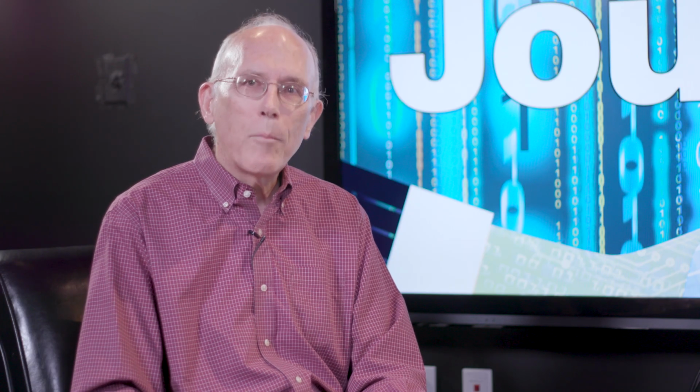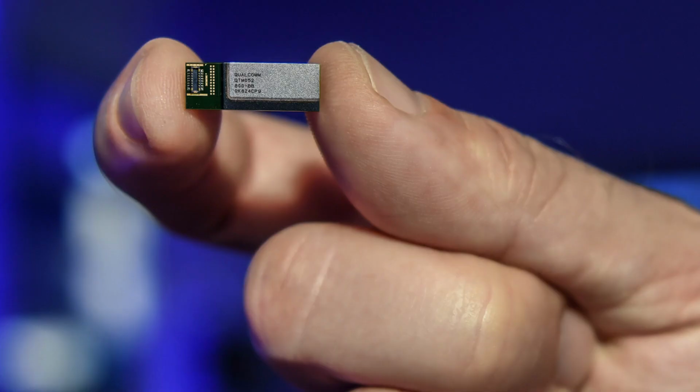And speaking of that, you mentioned Qualcomm. They had quite an interesting announcement earlier this week of some 5G modules, both covering the millimeter wave band and the sub-6 gigahertz bands that have been identified for 5G. So the millimeter wave, what they call antenna modules, actually integrate the new radio transceiver, a power management IC, RF front-end components, and a phased array antenna, all in a little module that kind of fits between your fingers. They have support for the 26.5 to 29.5 gigahertz band, the 27.5 to 28.35, and the 37 to 40 gigahertz bands, which are all designated 5G bands.